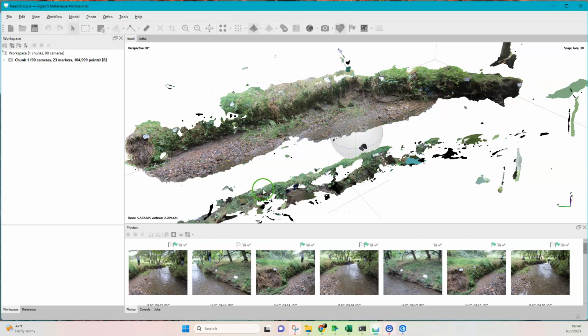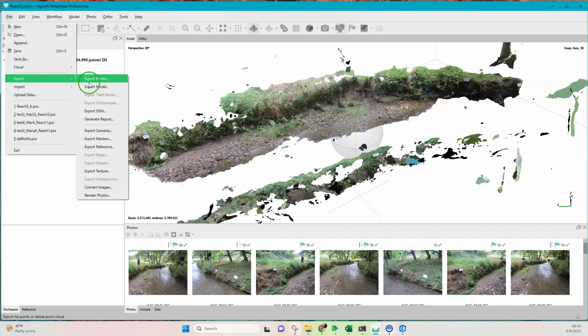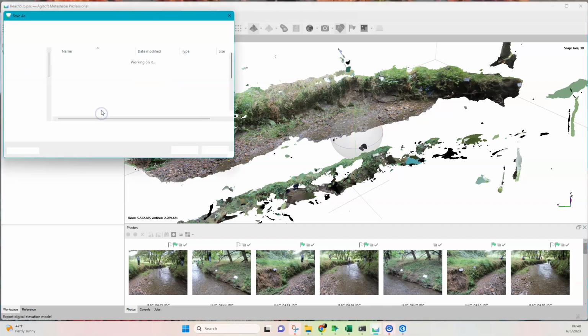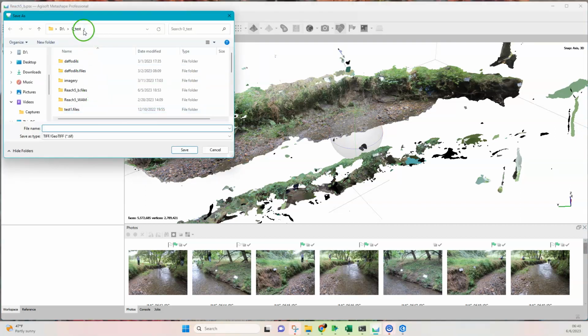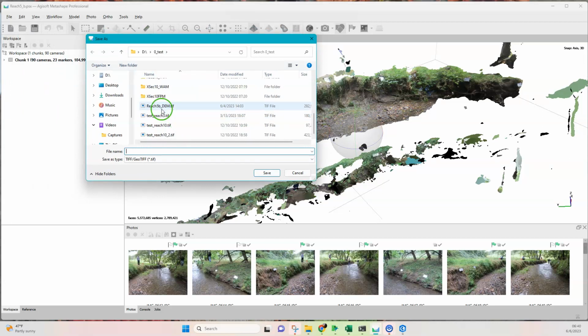And so that's what we just built. That DEM step was building an actual two-dimension rendering, a really fine-grained rendering of what this model tells us. And before we're done, we need to take one more step, which is exporting that DEM so that we can use it in ARC. So I just go to File, Export, and I say Save DEM. I've already done this once.